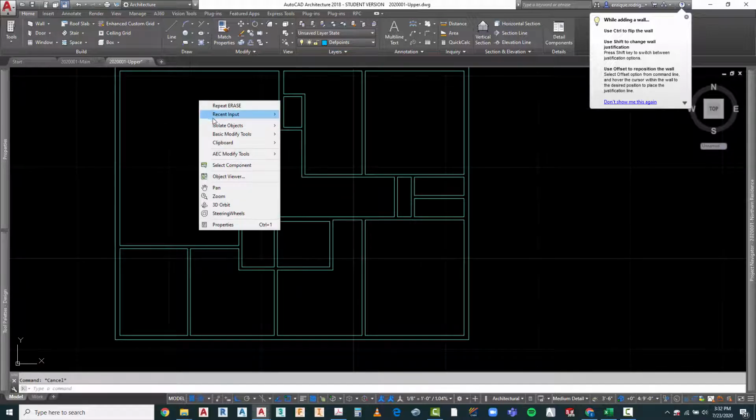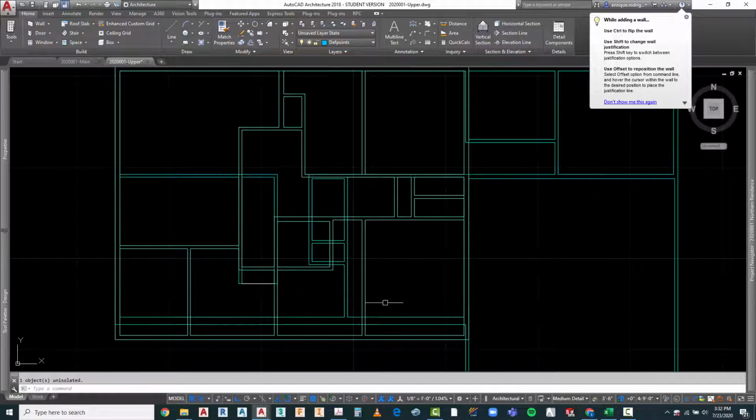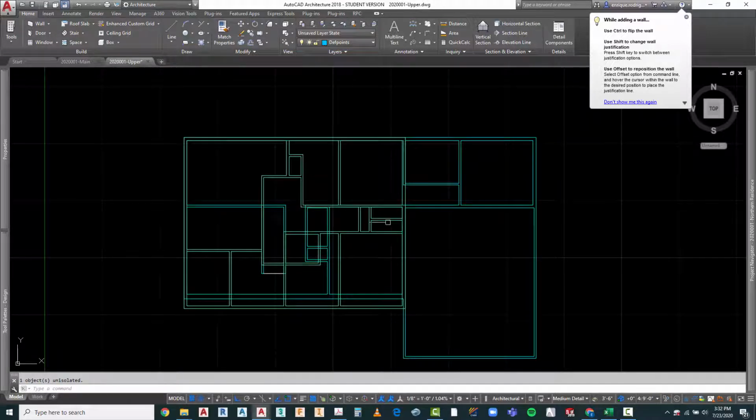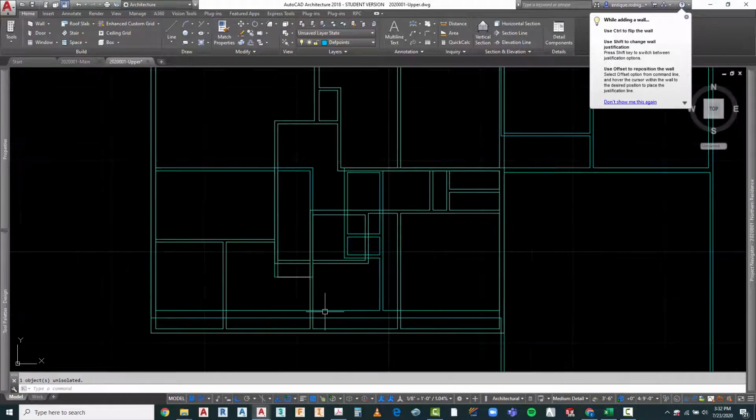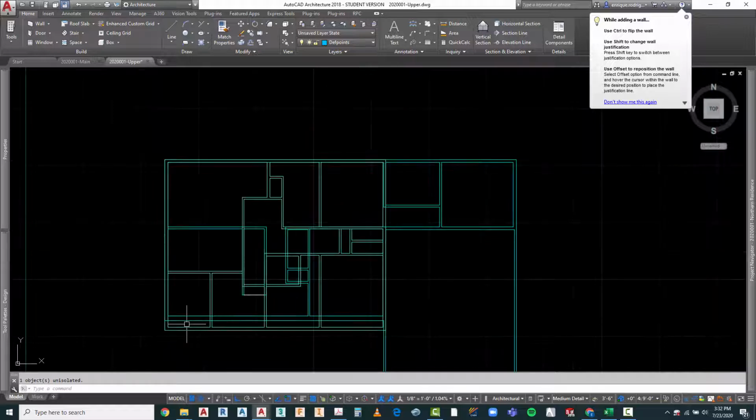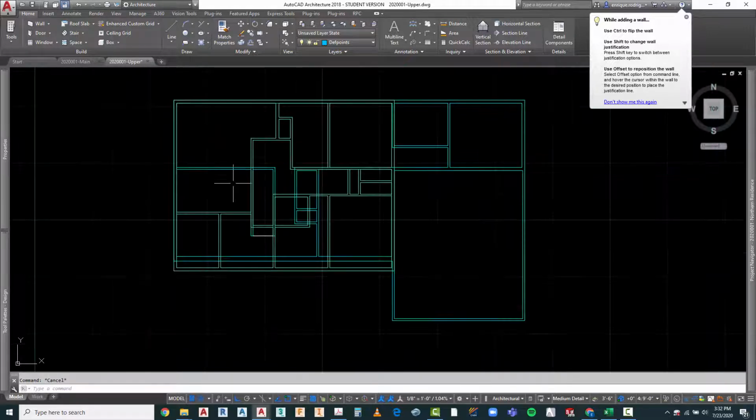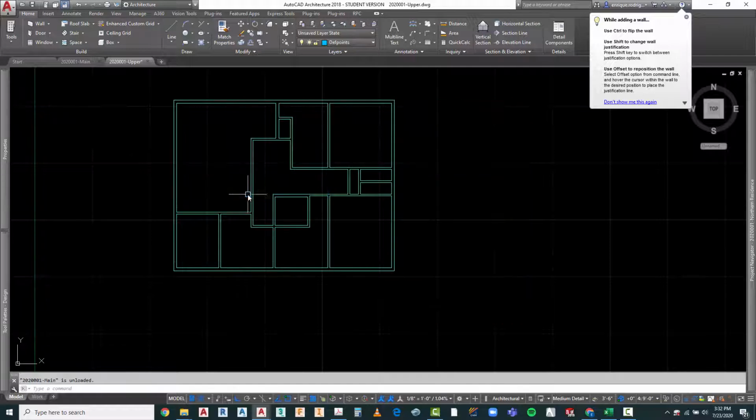I'm going to go ahead and go back to objects and object isolation, and I can see them now in collaboration with each other on how things work up structurally. So we know anything that has to do with a bearing wall condition is held up there. We've got the same conditions in here. This is a 2-foot overhang. Everything looks great. So I'm going to go ahead and leave that on the XRef right now, but what I'm going to do is I'm going to right click this time and I'm going to unload it. So it's still there, but it's unloaded.